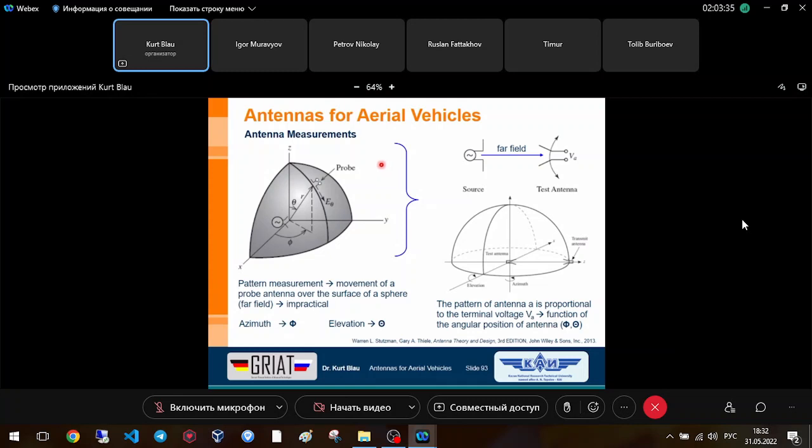If you calculate, for instance, the observation distance must be 3 wavelengths, then in case of an antenna for 1 megahertz, the distance is maybe 1 kilometer or so. On the other hand, for very high frequency antennas, with very small wavelengths, if you use a high gain antenna with a large dish, you can also see from this far field formula that you have to bridge very large distances. We will see this later on.